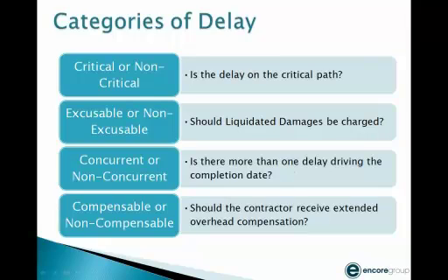If you look at the analysis that I showed you a while ago when we were talking about the as-built, how the plumber just let his work slip and slip and slip, right? Well, a lot of times someone would come back and say, oh, that's a concurrent delay. When in reality, it wasn't a concurrent delay. The plumber was managing their flow. Now, at some point, that delay became concurrent. And what that point was is something that you have to look at and analyze. That delay did become concurrent at some point, but for a big chunk of that the plumber was just managing their float.